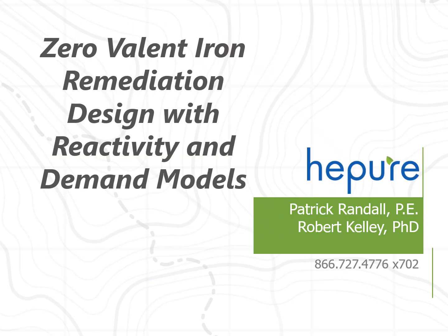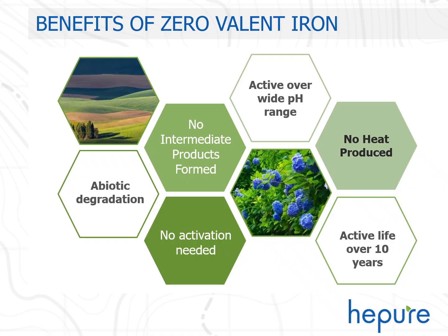Today, I want to discuss how we design remediation systems using zero valent iron, ZVI. There are many benefits to ZVI over other methods. It is an abiotic degradation, and I will go into that in more detail later. There are no intermediate products such as DCE and vinyl chloride formed.